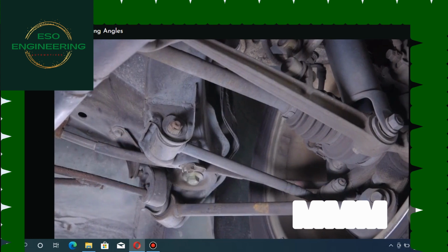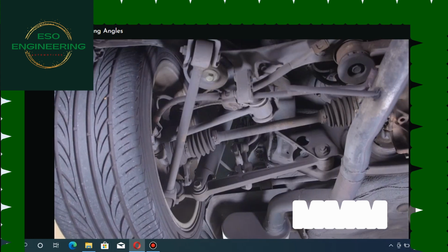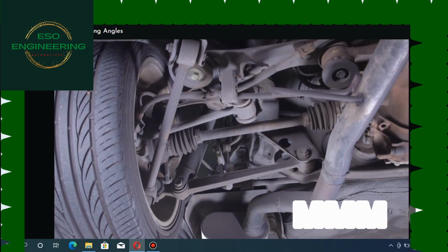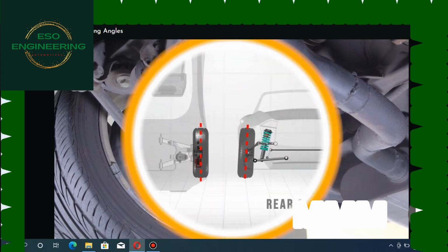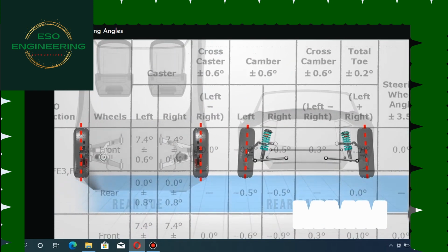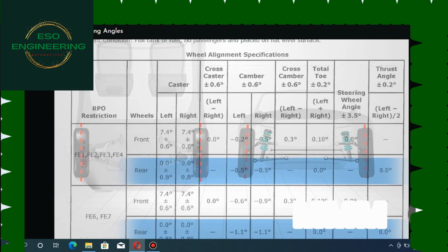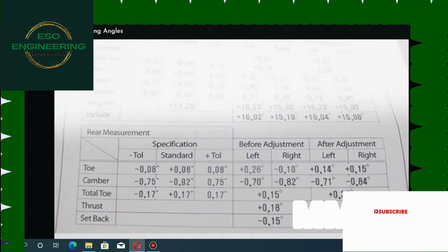Most modern day passenger vehicles now have adjustable rear suspension arms and mounts. Rear toe settings are quite common, whilst there is an emergence of rear camber adjustments available. As with the front, the rear measurements have the same significant impact on the vehicle dynamics and tyre wear. As vehicle suspensions become more sophisticated, similar tests and settings are available for the rear suspension systems.